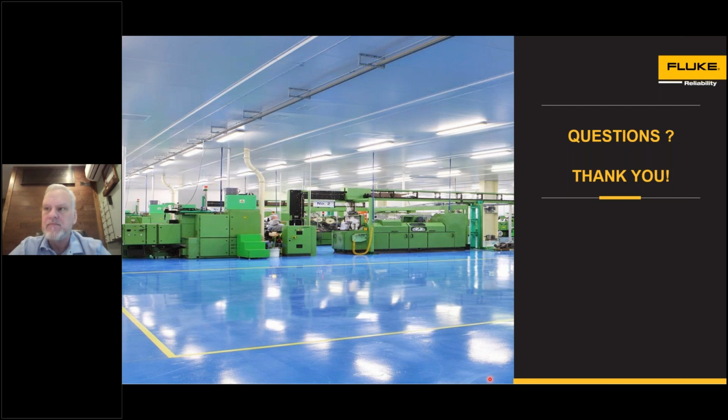The next one I have: would a wireless sensor be a good application for a conveyor? All right, that's an interesting question. Yes, sometimes. The answer is sometimes. When we look at conveyors, there are many different types of conveyors, and many different speed outputs. Sometimes that speed output falls into a low frequency range. That doesn't mean that the drive unit isn't a good application. Oftentimes the motor and the gearbox have many or all the shafts that are above 600 RPM.